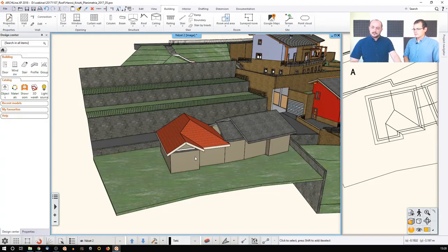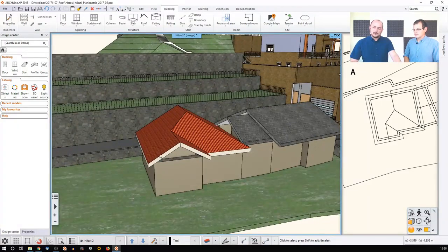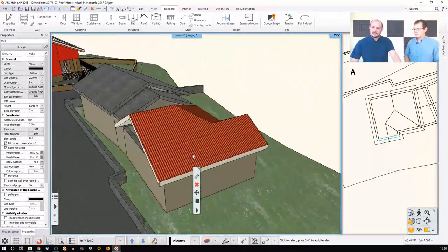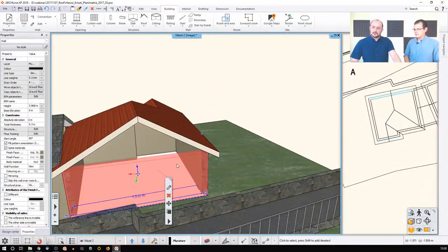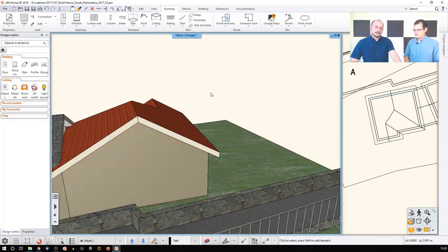And again, considering this here, there is no updated wall roof connection yet, which is for two reasons. One is that sometimes, like in the other case here, the wall is simply not tall enough. It's only coming up to this side, so I can just click here and say change height, and elevate it to something like this, and then it will solve itself.